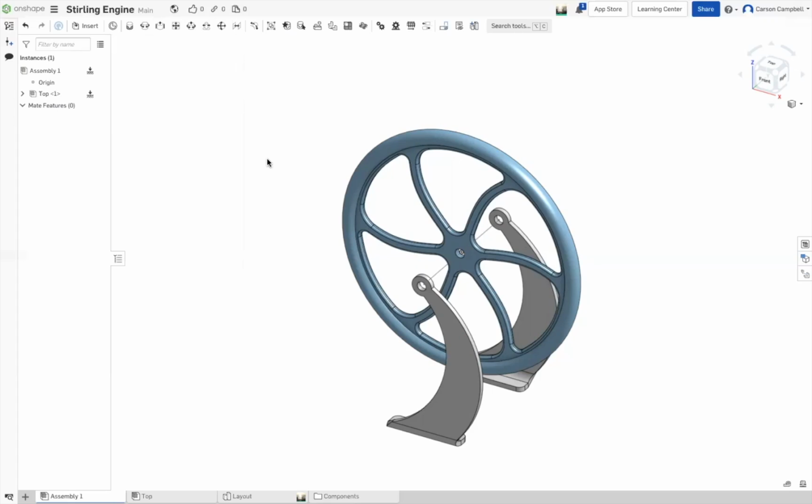When I define a library part that I'm going to use everywhere, let's say like a cylinder, and the cylinder goes in and out, that library part, the motion is defined. I'll go and I'll grab that assembly out of my library and I'll use it in a design. And when I fasten it all up, the cylinder still moves. I take that mechanism and I put it into another top level assembly. And even though all the motion is defined in the library, it inherits all the way up the chain. It is just totally revolutionary.